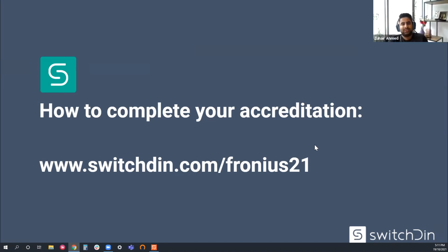Good question. So we already have a demand response controller, the DRM controller. I didn't discuss that in today's session. It's available. It's already added in our database, and it's also compatible with Fronius inverters. If you want to do demand response controls, we have added all 8 DRM modes, and there is a controller available in the same drop-down menu where a user can select peak shaving controller, multi-site controller, or any other controller. They'll also see a generic DRM controller. And as I said, Fronius is added in that database.